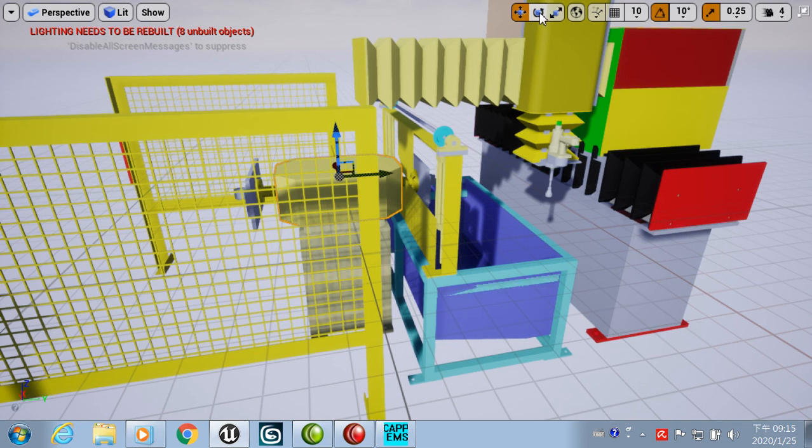Rotating about the Z, we have to press the button on top of the light blue circle, and put the cursor around the circle. You will see the C component will drive, and you will see the A component and the B component follow as the child of the C component, while the foundation does not move.